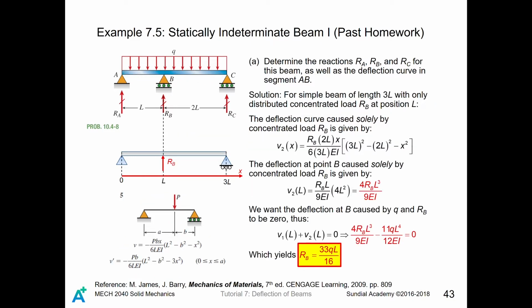So by taking this into consideration, you have to use another entry inside the superposition table, that is the single load one. Okay, so in this case, A and B inside the superposition entry. So A is L, B is 2L, and L now becomes 3L.